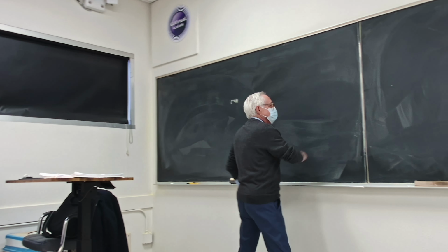In addition, I have Z1 equal to Z2, right? Because it's just straight. Whatever it is, it's a small component, but there is no elevation difference between these 2 points. Therefore, for mass, I have m dot 1 equal to m dot 2. We just call it m dot, mass flow rate. Okay, you remember m dot is rho velocity area. The density times velocity times area